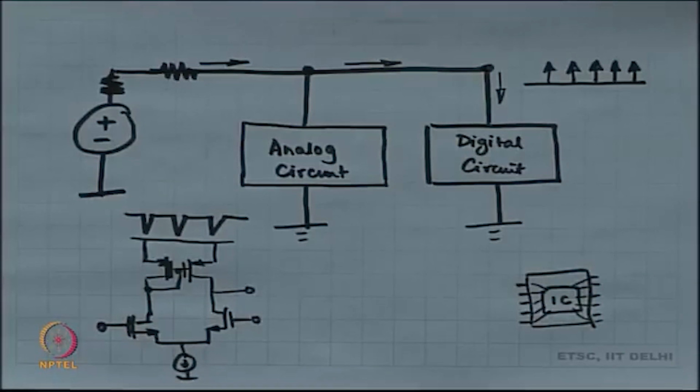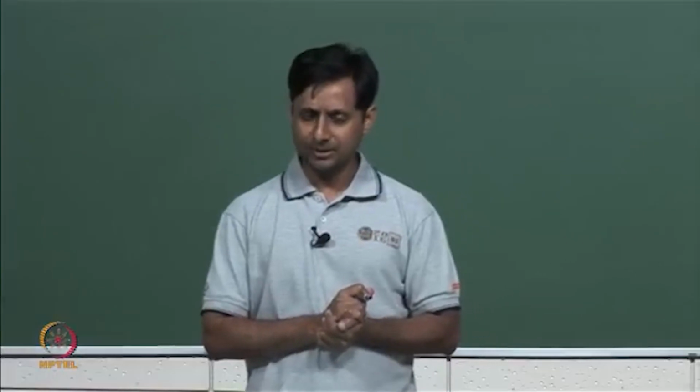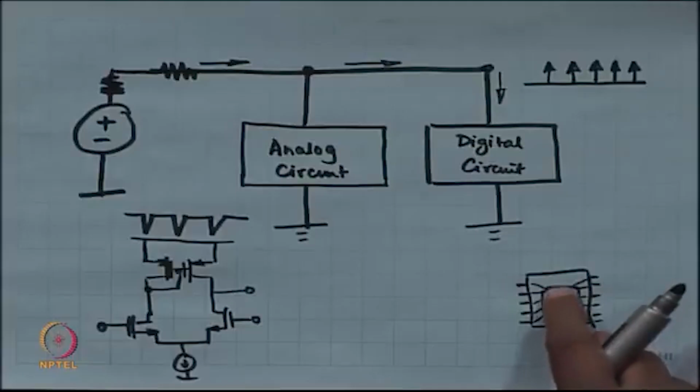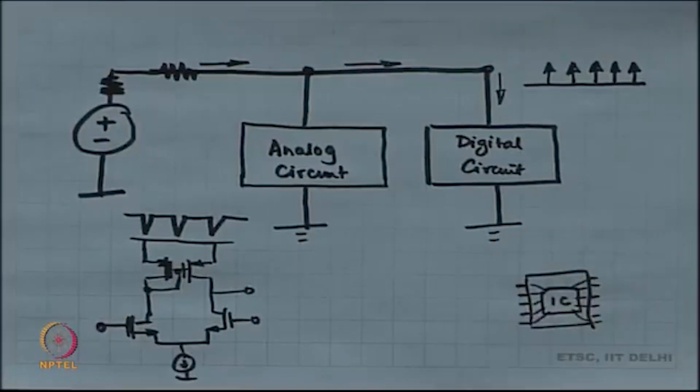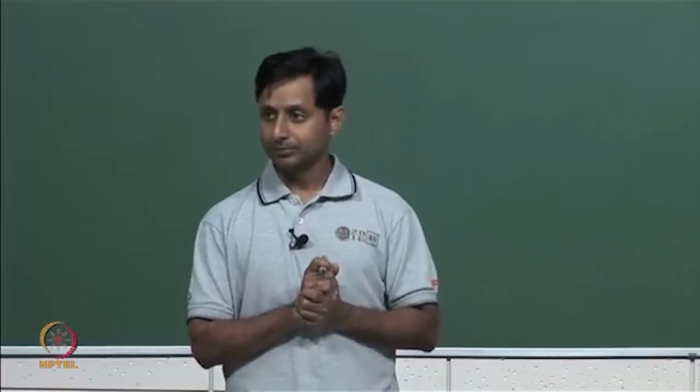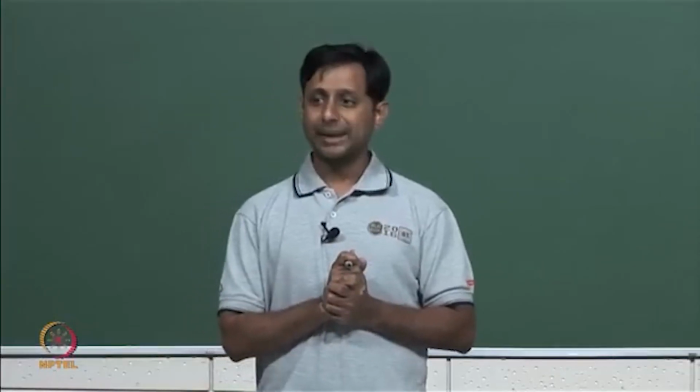Okay. They are made of gold because gold is the most malleable metal, right. You remember, ductile and malleable element, that is gold. So, typically these wires that connect the actual piece of silicon to the package are made up of gold. They are very thin, diameters could be as low as 0.025 millimeters. Okay. That could be the diameter.